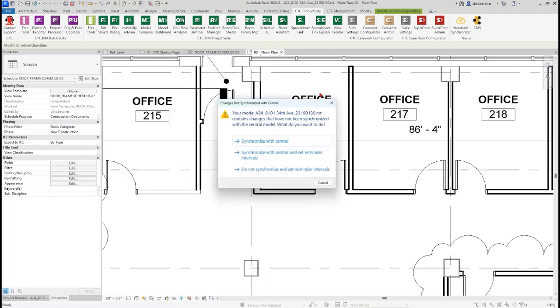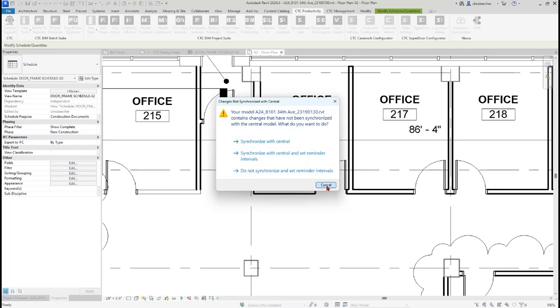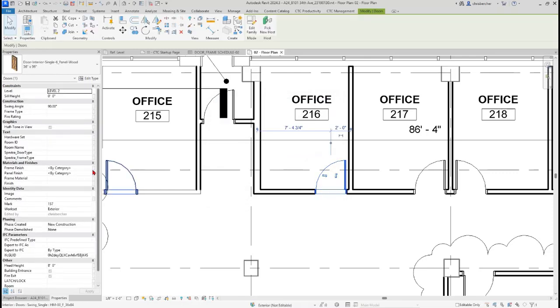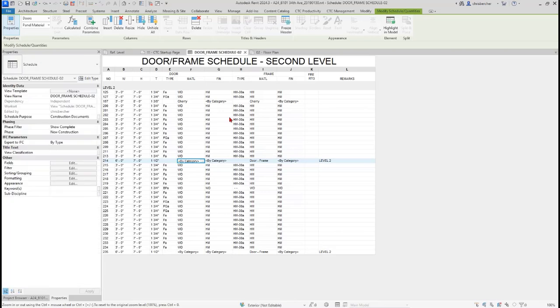And if I go here and grab this, so I got my finished properties here. They're empty, right? Nothing's there. If I go back to the schedule, it should have refreshed by now. There we go. Sometimes Revit, for whatever reason, doesn't refresh for me all the time really quickly, but here it is. So it auto mapped the panel material and the frame material in this case and gave me what was already defined in the family, which is fantastic. One less step for me to worry about.